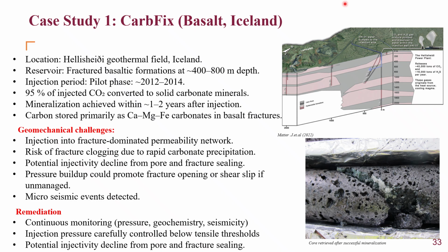About 95% of the injected CO2 was converted into solid carbonate minerals. Some of the geomechanical challenges that we faced were that injection into the fracture-dominated permeability network meant that the permeability was going to be reducing over time. Risks of fracture clogging due to rapid carbonate precipitation was one of the challenges.